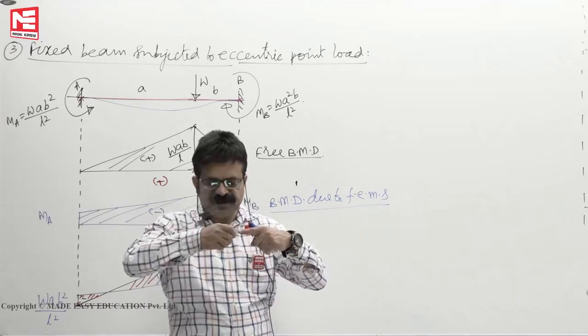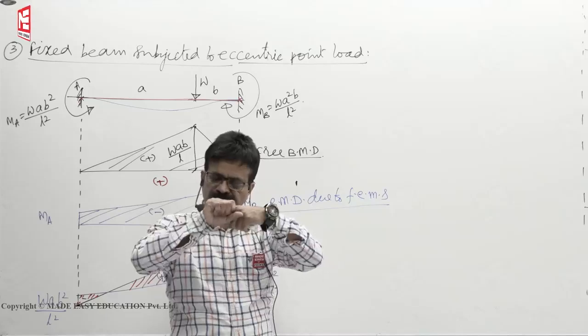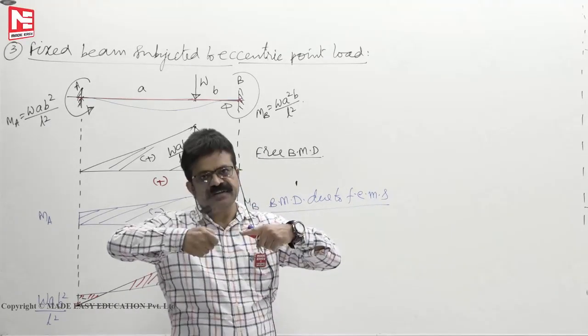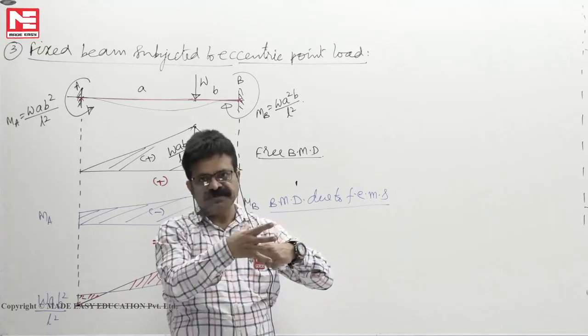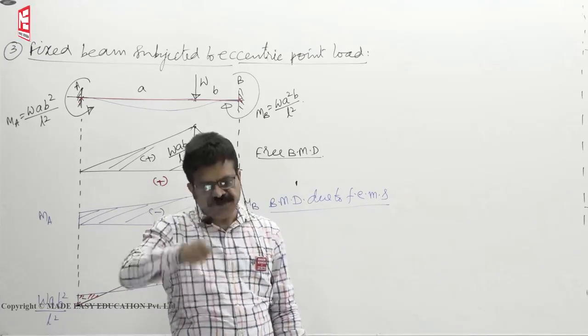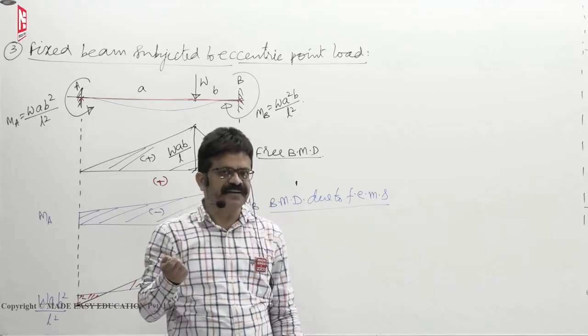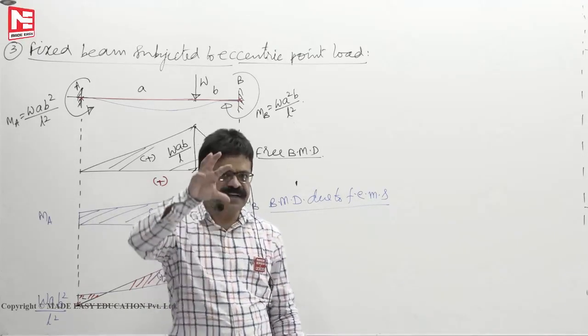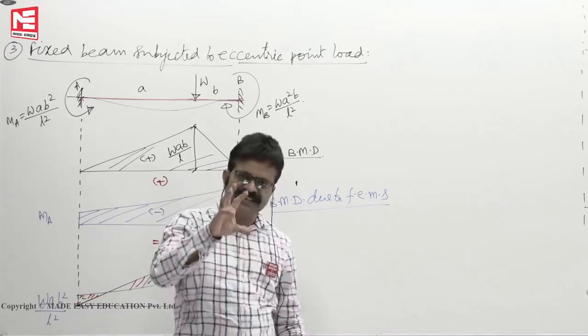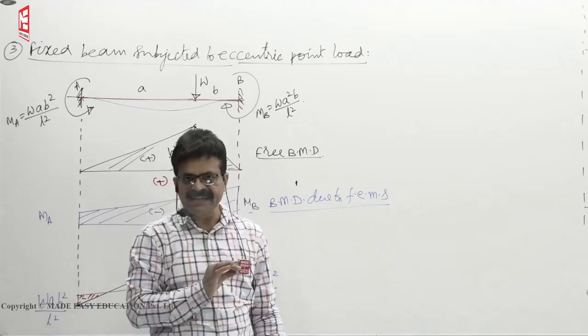Wire wound cylinders means, to effectively utilize the cylinders, wires are wound because when the fluid flows through them, to avoid the bursting of the cylinder, you will wind the wire. So before fluid enters, the cylinder is under compression. Now when fluid enters, the tension will develop, but net stress will be very less.